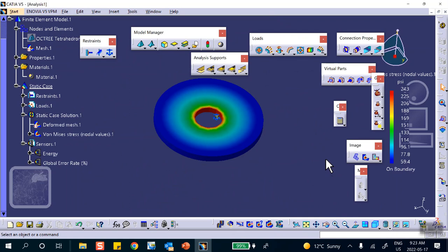This anchor or isostatic restraint is nothing but that 1, 2, 3 rule that I did for you last week. It automatically goes and applies the 1, 2, 3 rule to some nodes that you don't see. You can find it if you want, but it is exactly the same thing, and it does it for you automatically. So if you use this and get a bad result, you can't recklessly go ahead and use it every time the problem doesn't work. It'll run, but it may not be the problem that you want to solve. So I don't want you to lose much on this.